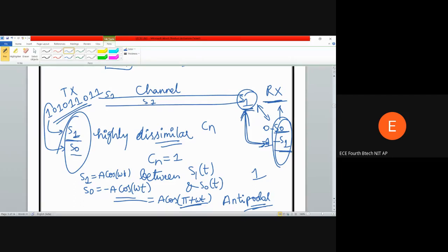There are specific advantages if you use orthogonal signals in communication. We will be having specific examples of those advantages. So this is the place where we will be calculating the similarity between two signals. Now, in digital communication, to be more specific, we will be calculating the correlation or similarity between two signals. There, this correlation coefficient might be useful.